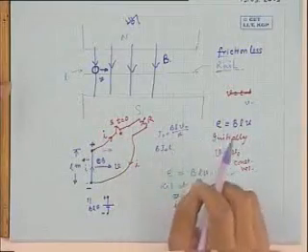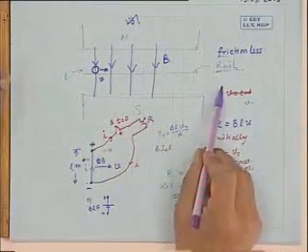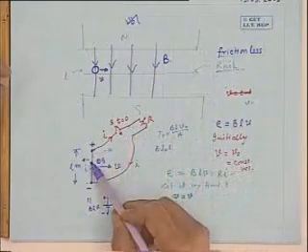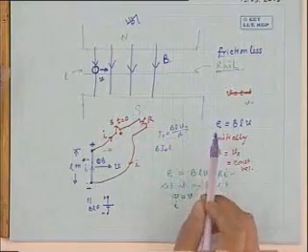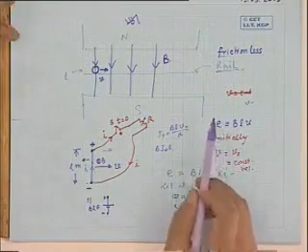And the prime mover, in this ideal situation when there is no frictional loss on the rails or anywhere else, initially, when you are not taking any power out of this generator, the input power provided by the prime mover should also be zero. But the moment you start taking out power, because there is now an opposing force, your prime mover should be able to provide that extra bit of force, always matching the force exerted on the conductor because of loading. That way you can run it.